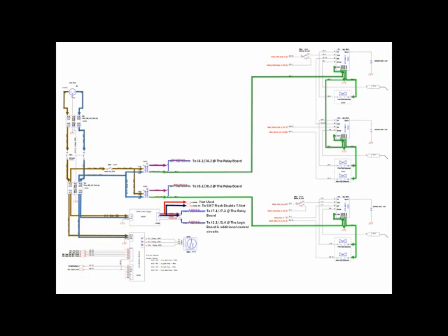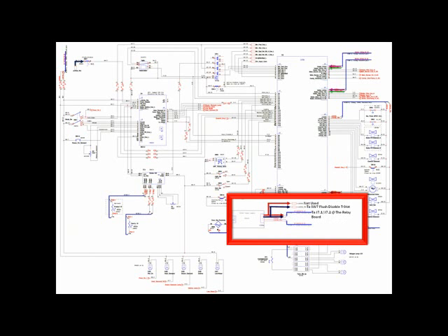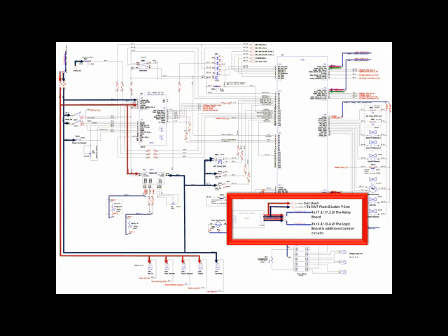And finally, it supplies several other locations on page 1 of the diagram. While looking at page 1, we see 24 volts enter and feed the mode switch, the steam on demand button, indicator lights, the logic board, the temp controller, as well as the cavity light, vent, and fan speed switches.